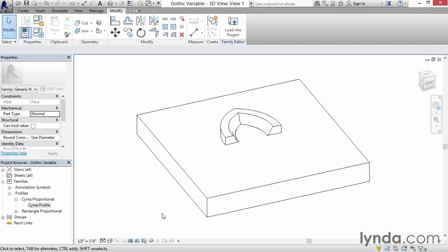You can do both things directly here from the family. If you want to link up those additional parameters, that's your option as well. But it gives you a great deal more flexibility when building these sort of common profile shapes and allowing you to set them variable so that if you want to use them in different contexts, it's just a matter of dialing in new numbers and you're still using that same basic shape, but you can use it in multiple families that way just by adjusting those little values.